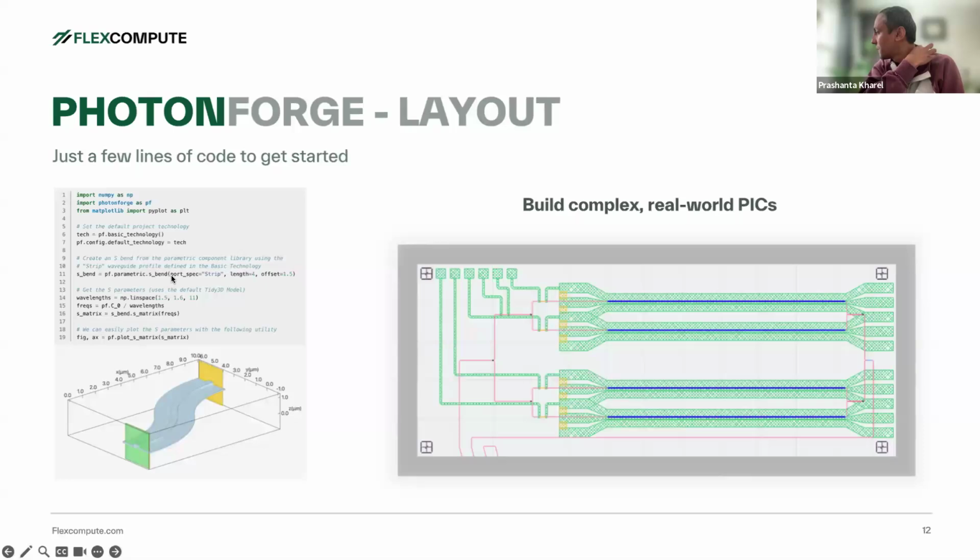They're called P cells typically in photonics, or even electronics. And we have a lot of these parametric components. We also have a lot of basic geometry functions, so you can draw any GDS layout. But the nice thing is once you build your component, running a simulation, or in this case, getting an S matrix for that component, is as simple as just saying component.S matrix and giving it a frequency range.